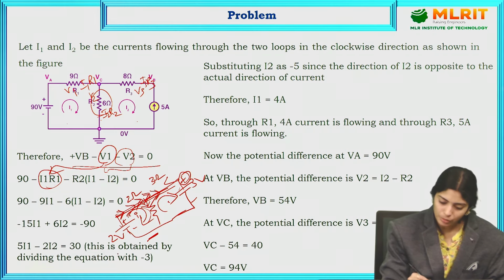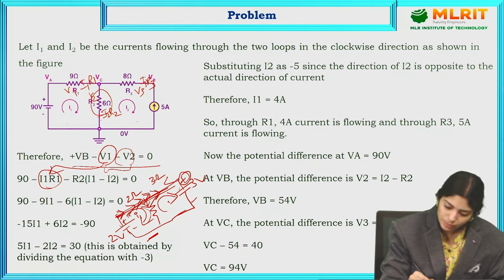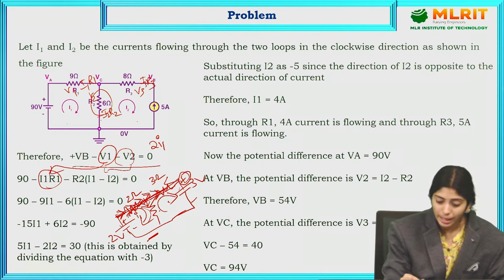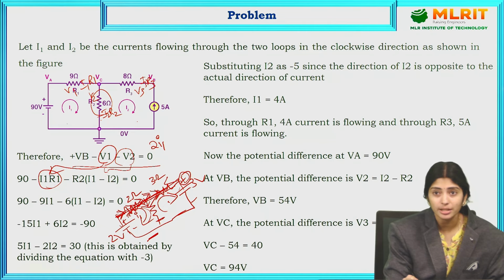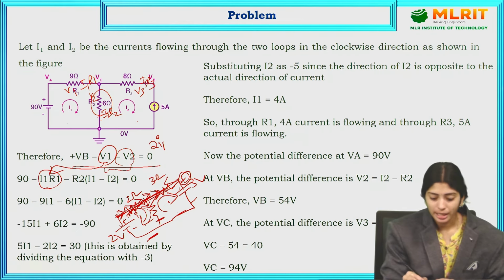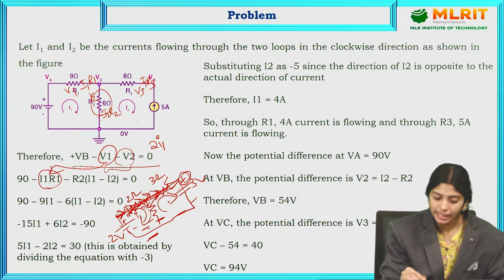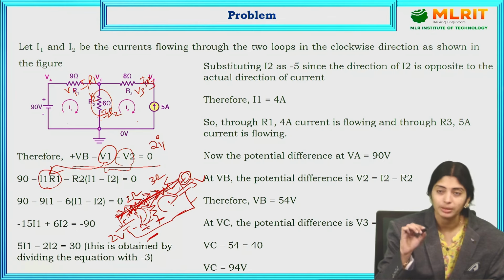So now how we can write the equations for this by applying the KVL. So 2 into I1. Okay, up to here it is okay, but this resistor is there, it is common for loop 1 as well as for loop 2, means loop 1 current is also flowing, loop 2 current is also flowing here. So in such cases, if we are considering the first loop, then we have to take this amount of current as positive, and according to this current will be negative.